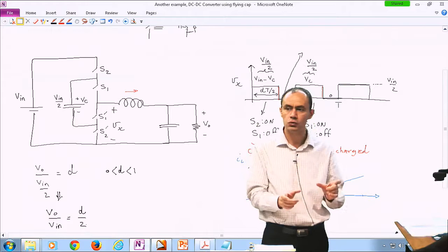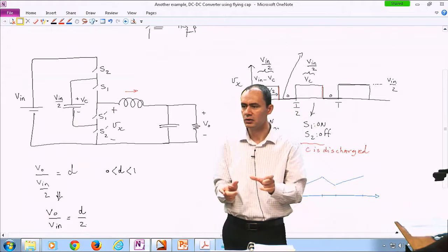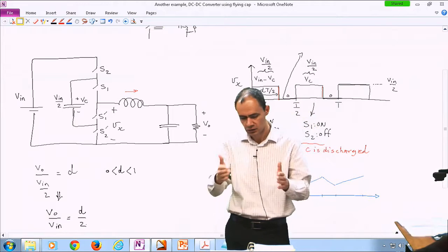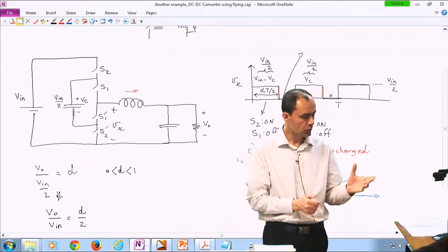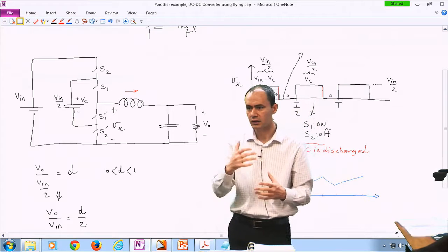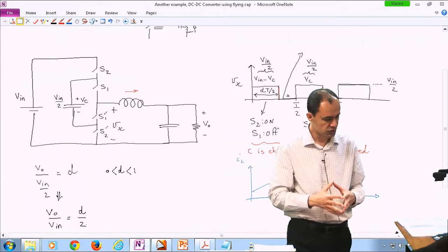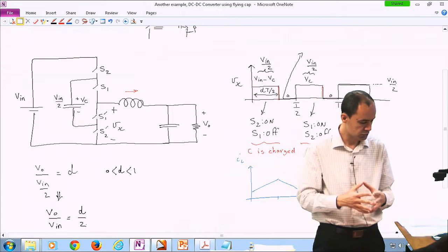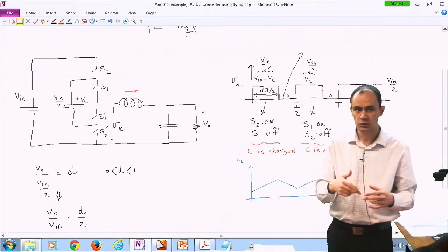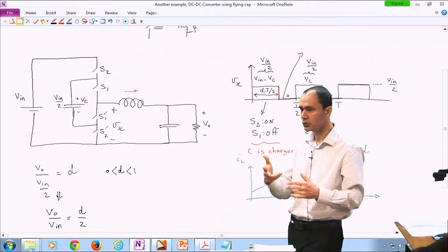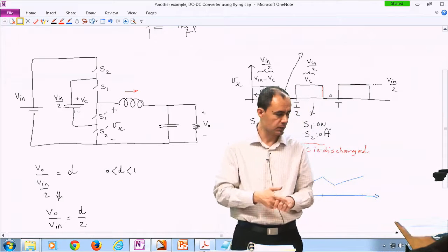So either you have to use 2 buck converters cascaded with each other, so each one of them kind of shoulders the load, or use a topology like this, which is directly doing that. Using 2 converters in cascade may not be the best choice, because then you have 2 inductors, 2 capacitors. It's a 4th order system. Controlling the system may become a problem.